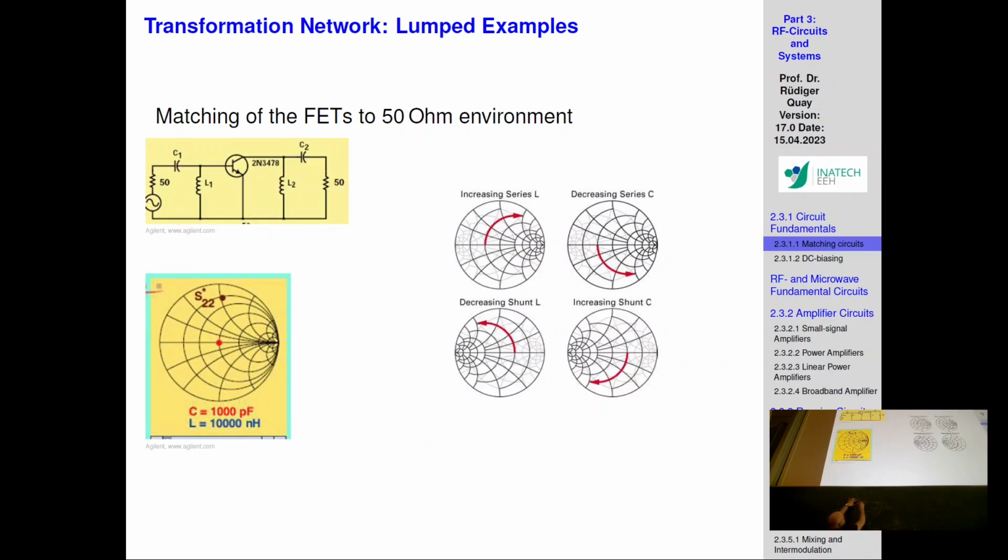And how do you do that? By adding an inductance. A series inductance: you add some microstrip line just to the output of your amplifier. You have this amplifier we saw, with the gates and the drains here, and the sources that were combined to each other. To this, you add the microstrip line, just like that. And adding the microstrip line increases your inductance.